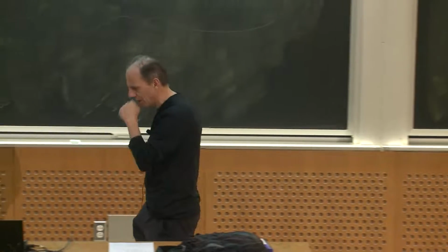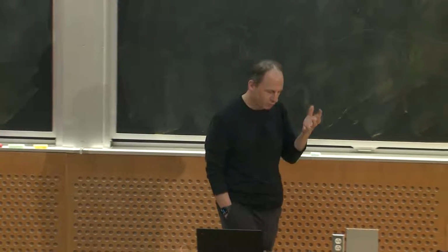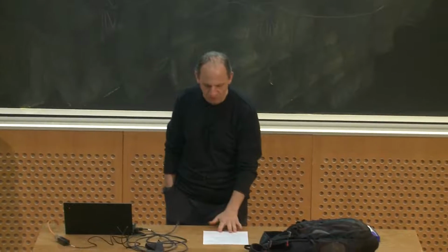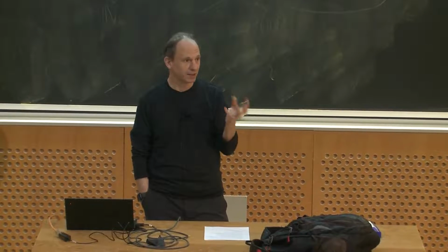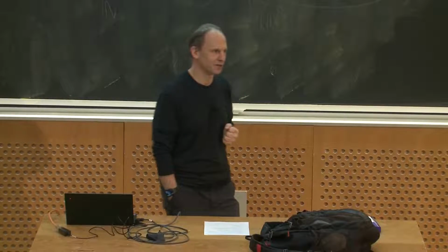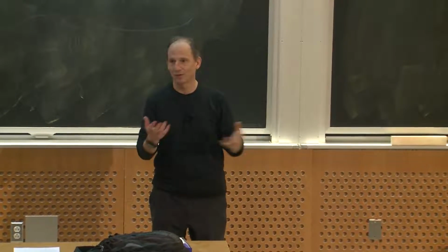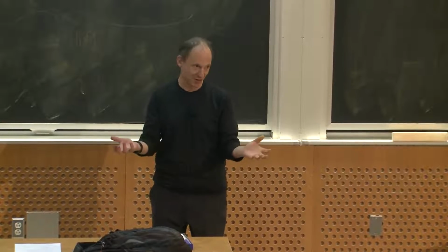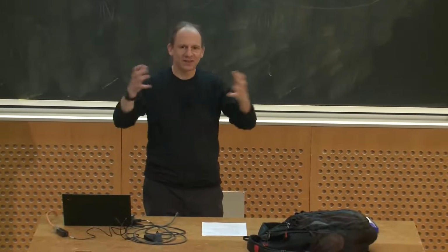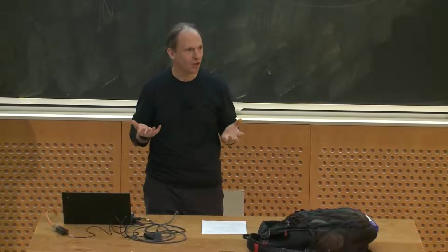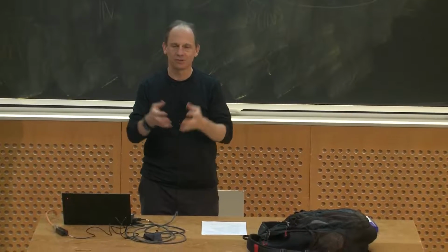Okay? So, if I'm going to design a magnetic component, I really have to think about loss. And loss is important for two reasons. First, magnetic components tend to be the dominant source of loss in a converter for the most part. So in a typical design, if you don't do a good job on the magnetics, your efficiency is going to stink. The second piece is that what sets the size of the magnetic component is often the loss. What prevents you from making things smaller is that if you make it too small, it'll get too hot and you'll be out of luck.